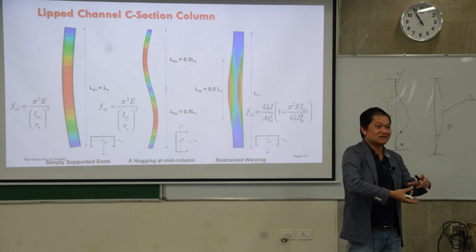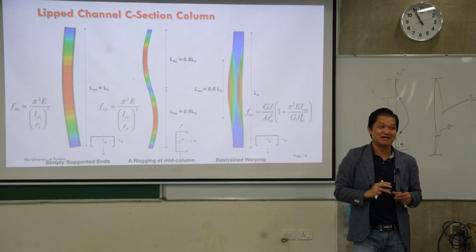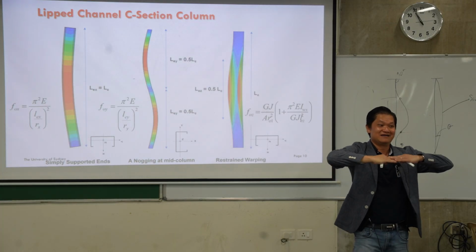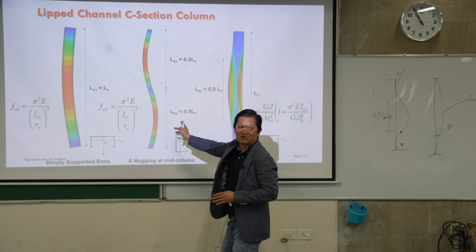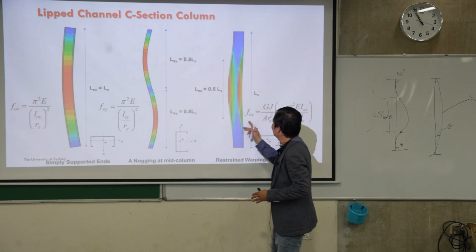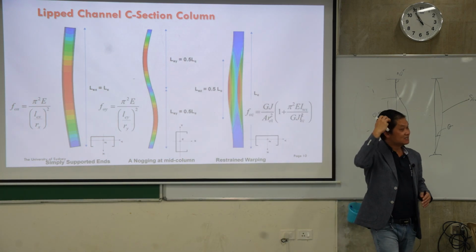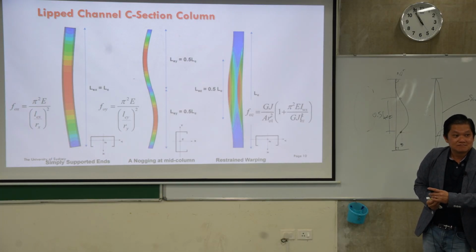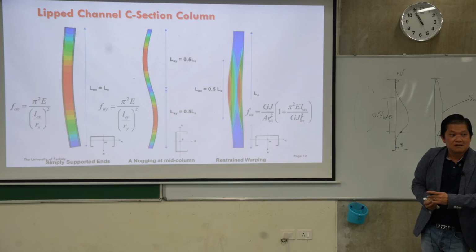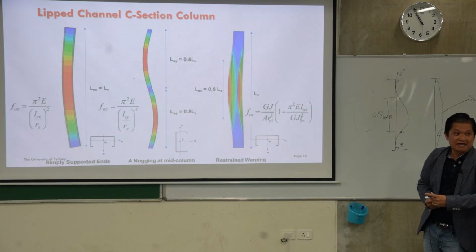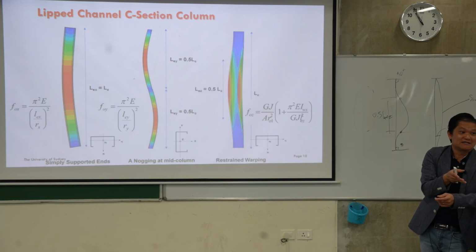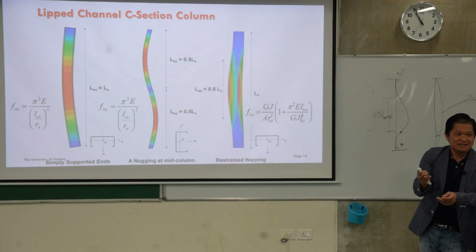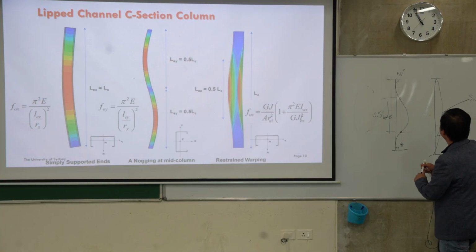That depends on the twisting rotation, not about this one. Right, so this is flexural displacement, but this is torsional displacement. I'm asking whether it is torsion, rotation, or that warping. It's restraining actually the rotation, right? Yeah, the warping affects the rotation. The warping is similar to the column here.